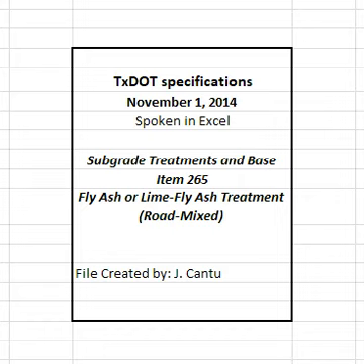2.1 Lime. Furnish lime that meets the requirements of DMS 6350, lime and lime slurry, and DMS 6330, pre-qualification of lime sources. Use hydrated lime, commercial lime slurry, or quick lime as shown on the plans. When furnishing quick lime, provide it in bulk. 2.2 Fly ash. Furnish FA that meets the requirements of DMS 4615, fly ash for soil treatment. Use Class CS or FS as shown on the plans.